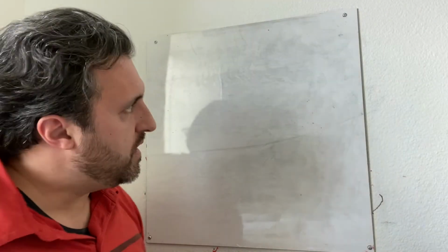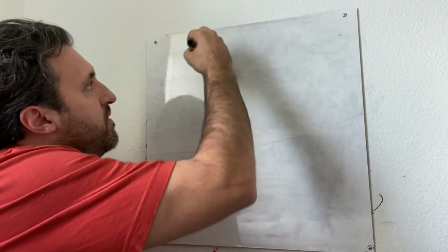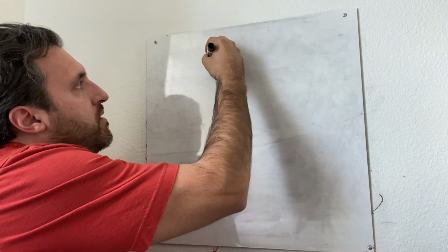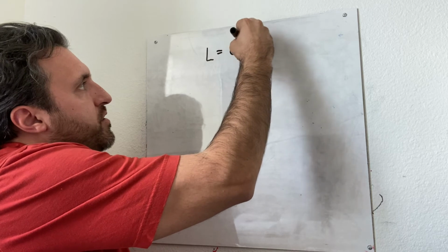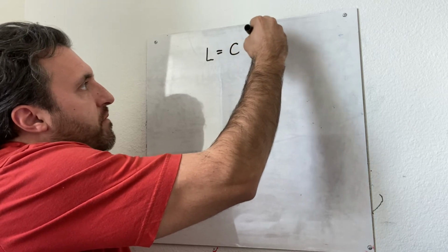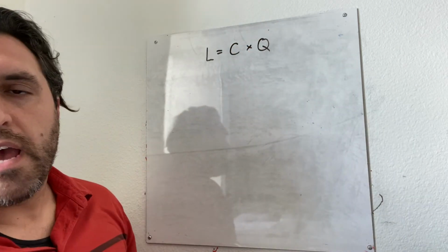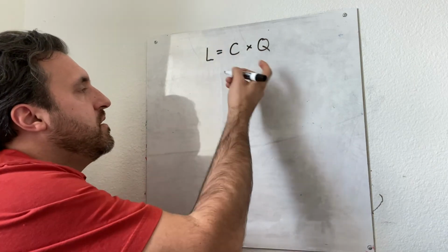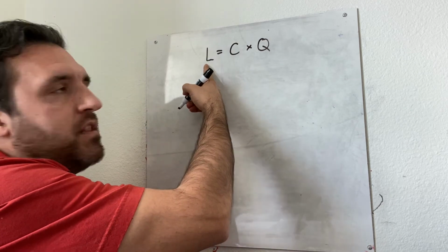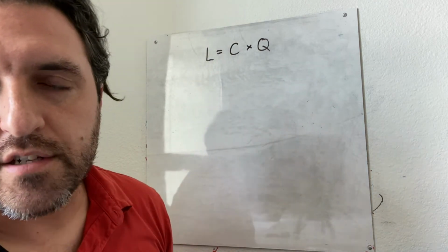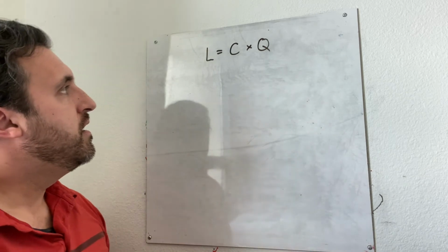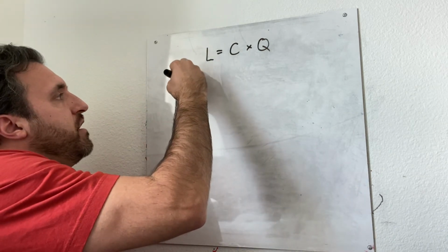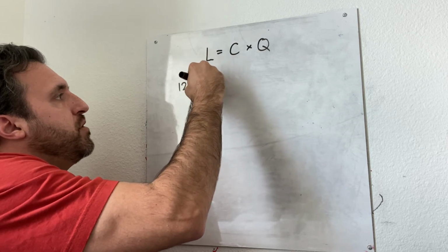So in both of these example problems, we are making conversions between concentrations and loadings. So remember that loading is equal to concentration times flow rate. So if we have a concentration and a flow rate and we want a loading, we use it like this. Of course, in some cases we might have a loading and we're being asked for a concentration, so we would just rearrange that equation. Very simple. All right, so the first one to start out is we've got a flow rate of 120 gallons per person per day.